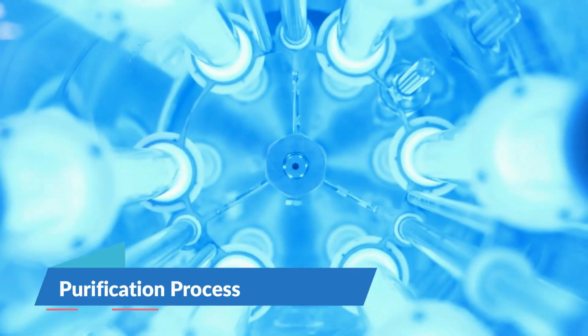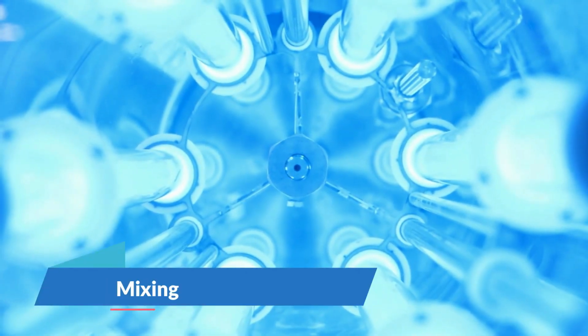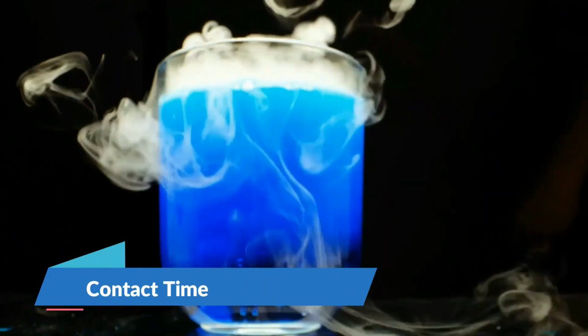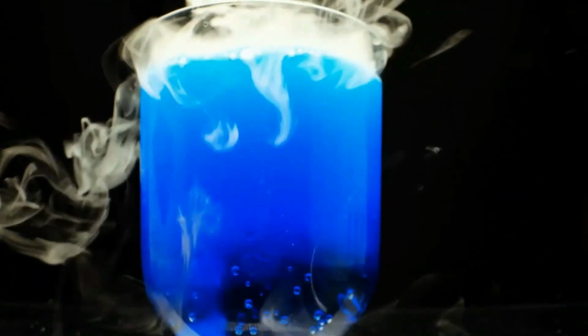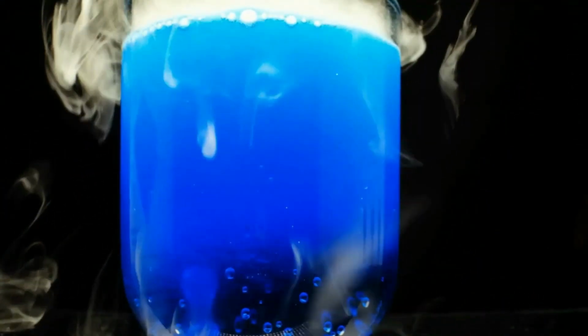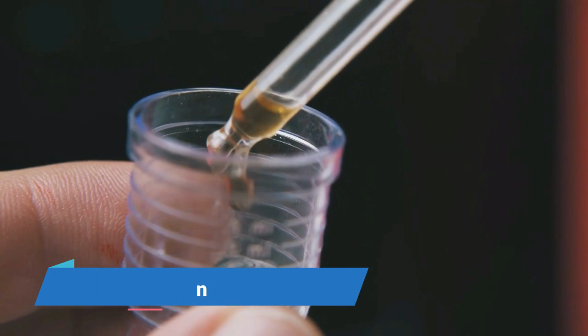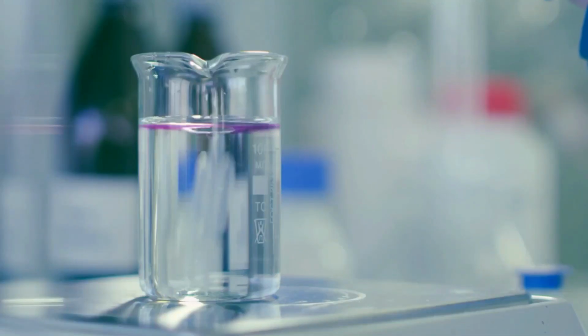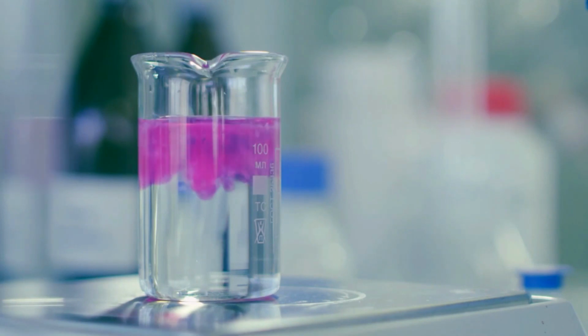Number 2. Purification process. Mixing. Dissolve the chemical in the water thoroughly. For gases or liquids, this may require stirring or shaking. Contact time. Allow sufficient time for the chemical to work. This time varies depending on the chemical used, but typically ranges from 30 minutes to several hours. Confirmation. Use chemical test strips to confirm that the right concentration of the disinfectant is present in the water after treatment.